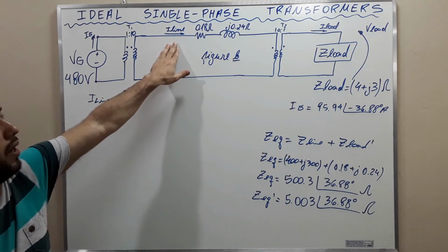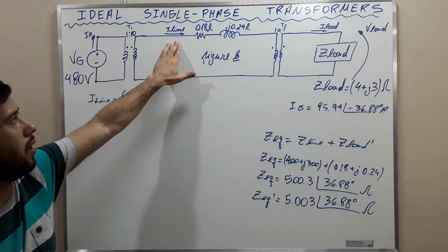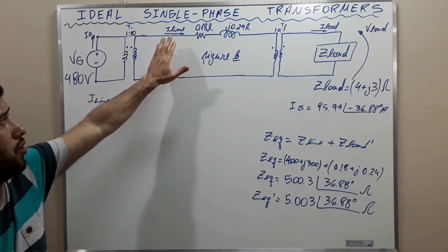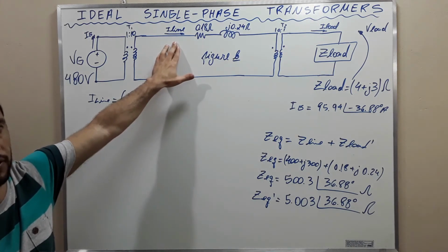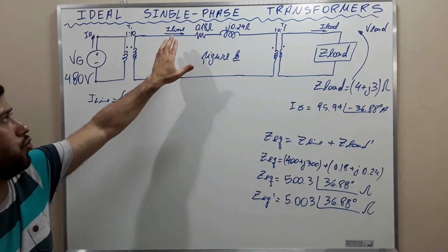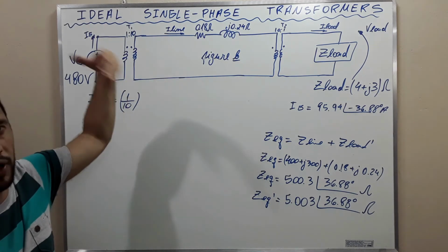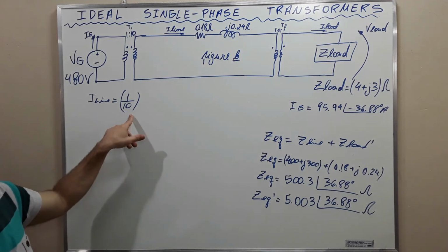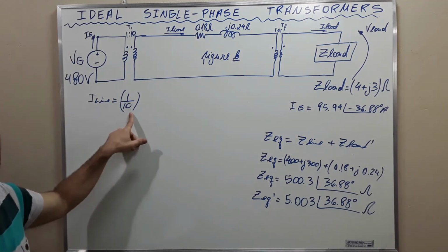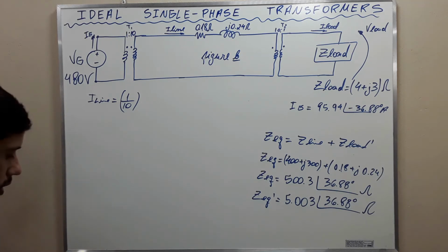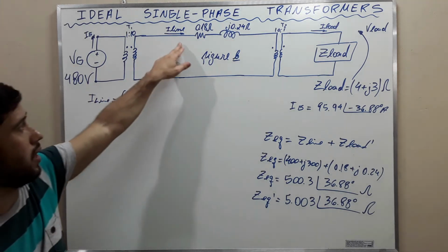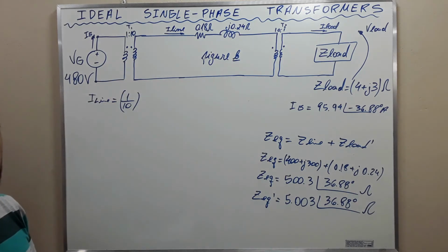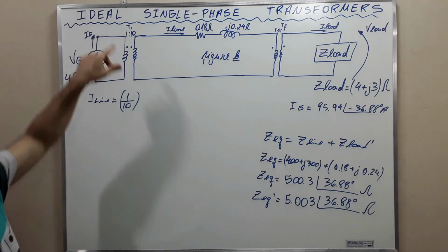Because high currents along lines are the causes of power losses. So we need to diminish power losses. And as we decrease the current, we increase consequently the voltage. So we needed to decrease the current to decrease power losses. The current along the line is going to be 1/10 of the current that flows in the generator circuit.